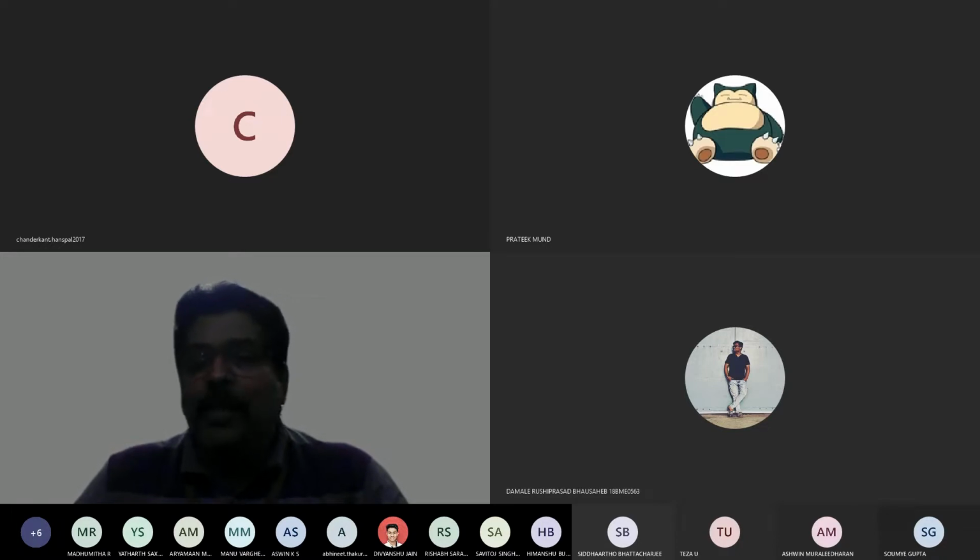And that element, if you look at, there are two forces. One is the force due to the lateral stiffness of the tire, that essentially represents your sidewall stiffness, and one end is connected to the string, the other end is connected to the rim, so that you are able to have the force due to this sidewall stiffness, and its elasticity and its deformation is responsible. Another one is the tension in the stretched string, so that tension component.